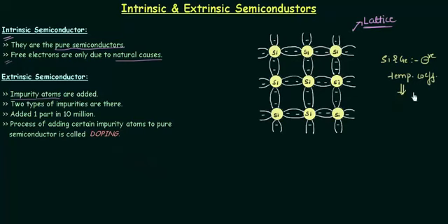This implies that with an increase in temperature, resistance will decrease. And in the case of conductors, the metals, the temperature coefficient is positive, and thus by increasing the temperature, the resistance will increase. So here we have the opposite of that, and you should keep this in your mind because sometimes they will ask it in multiple choice questions.